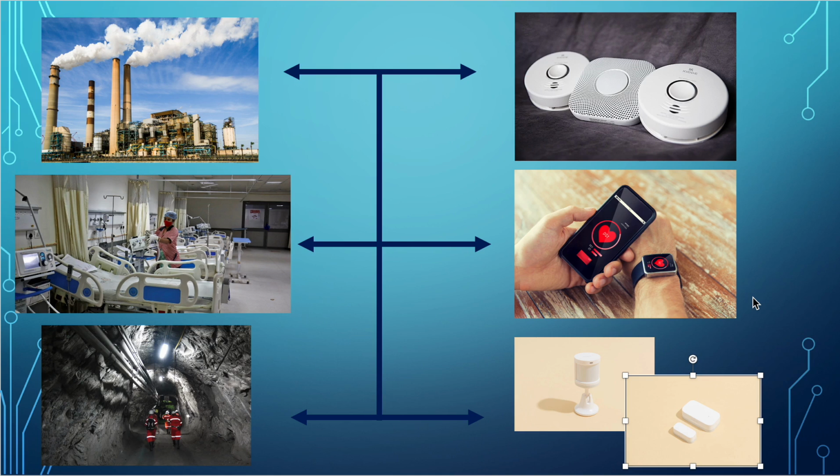It is better to use contact sensors to see that these pipes, joints of pipes or valves and everything are in place, either open or closed correctly, rather than humans going into these dangerous situations and checking them individually. The contact sensors can keep an eye on whether the seals are there correctly, open or shut.